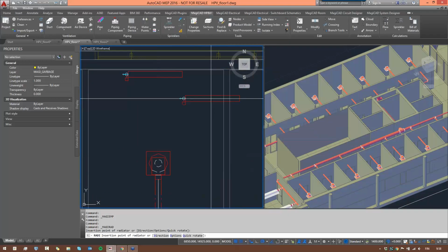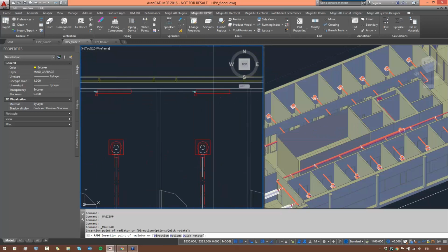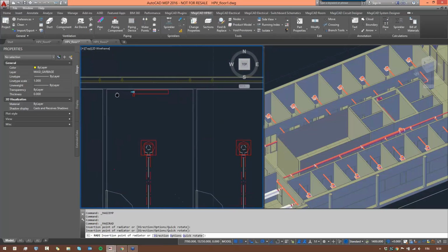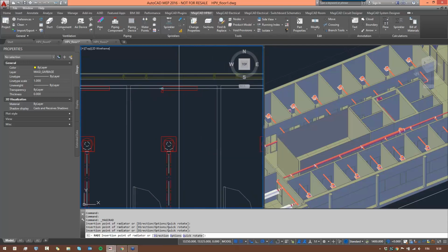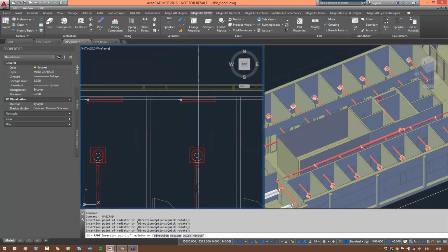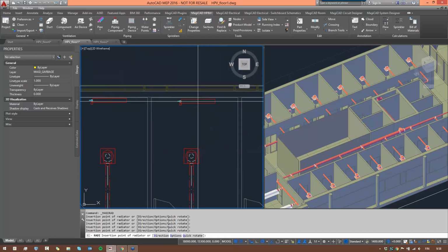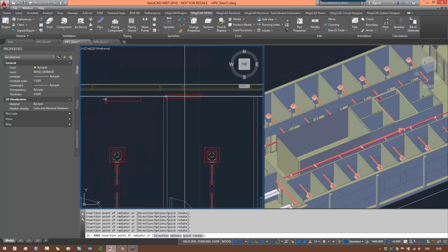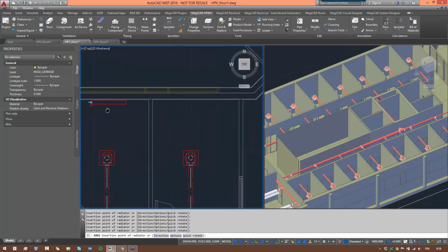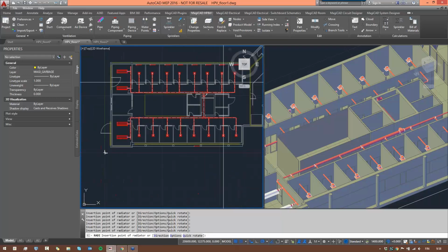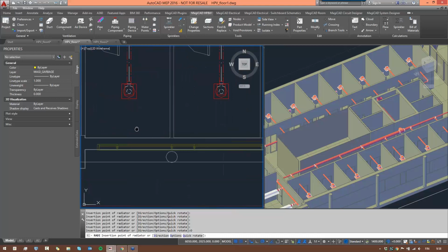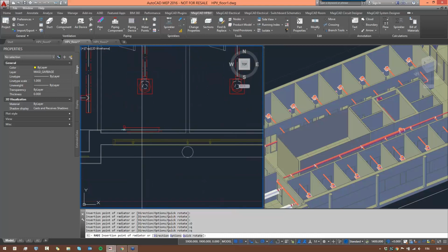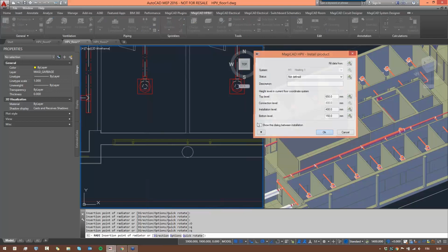Yeah, the height levels are good enough in the beginning already. Let's put a few of these in here, one in each room, of course. And I'm lining them up using the snap option here, so that the sensor levels are aligned. Let's check options. I'm using the same radiator, but with the mirror image, as I want it on the other side, and let's turn it that way. Yeah, high levels are good.